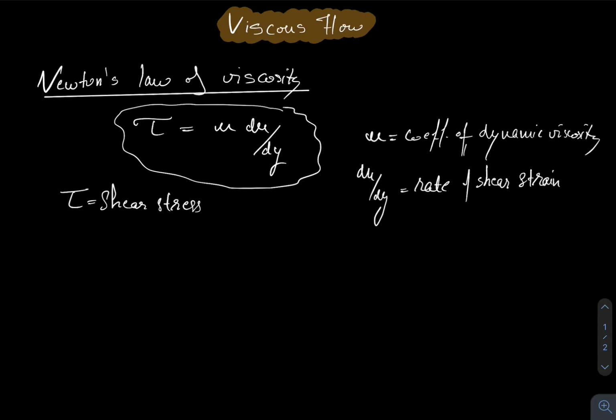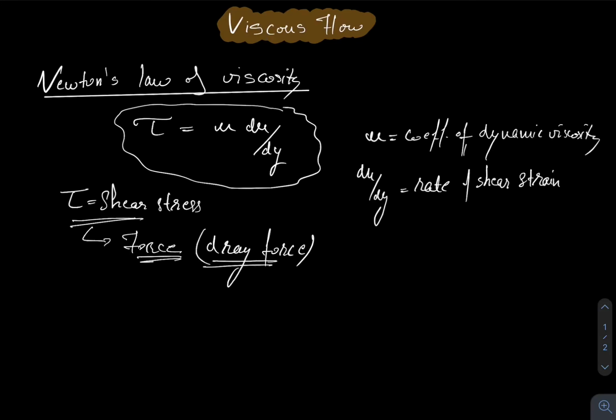Now because of viscosity there must be some loss in energy. This is shear stress. From here, by knowing the area, you can calculate force, that is the drag force. Because of viscosity, each layer will resist the flow of another layer, so there will be some drag force, that is resistance to the motion of fluid. Because of that resistance, some energy will be lost by the fluid itself in overcoming its own resistance. That was not considered until now. In Bernoulli's equation we have not considered such losses, but losses are there.